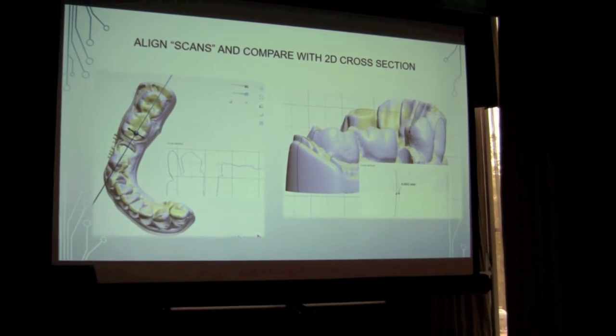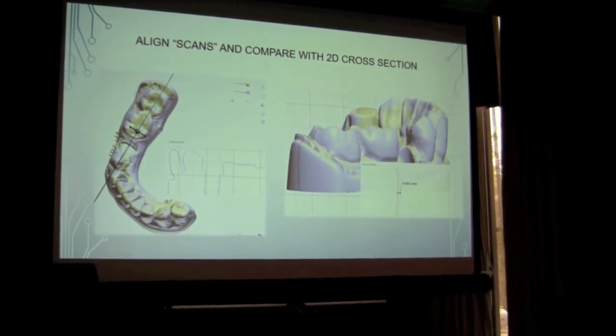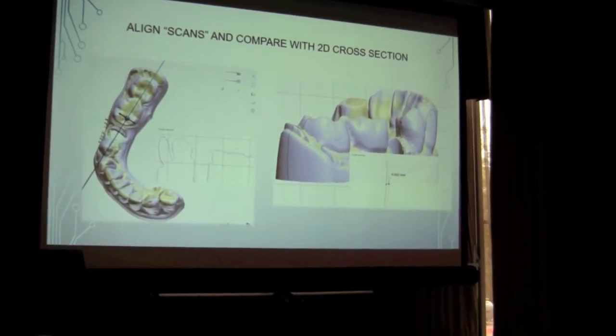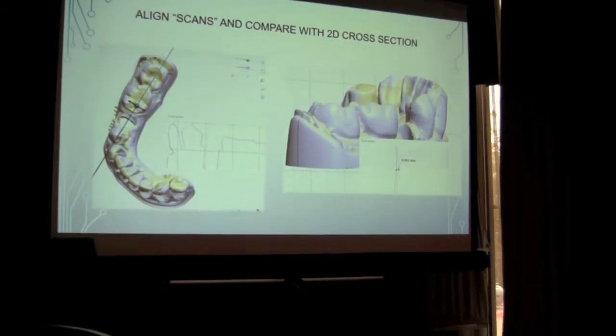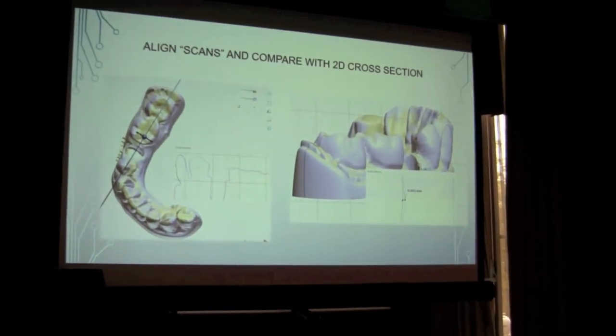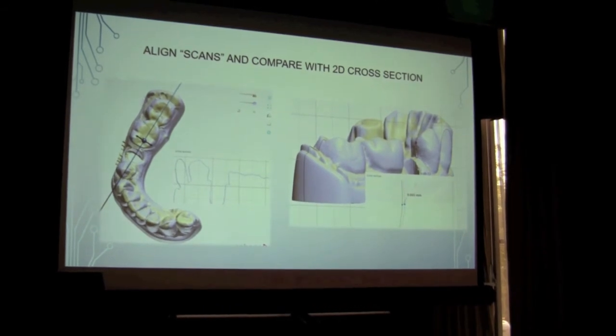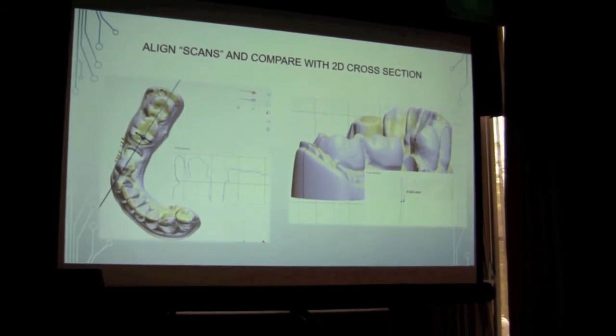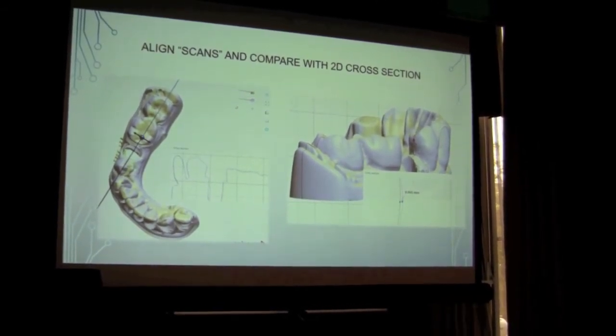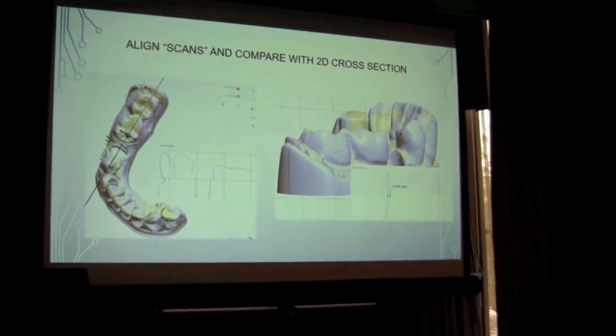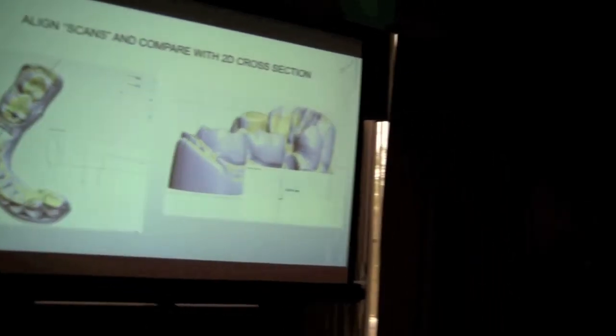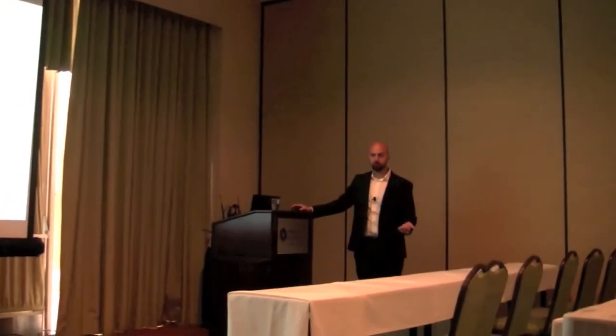I mean, that's huge. So what you have to do is then go into the software of the printer, and it really helps if you have an open source 3D printer. You can actually change your own scale factor to match until you have complete accuracy. So yes, you can do this in-house, and I highly recommend it, especially if you're going through and testing 3D printers from other companies.